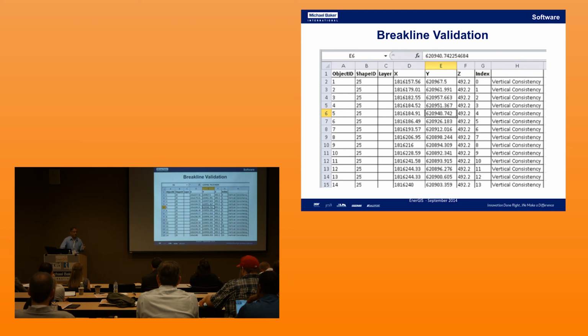And once you have the break line and the ground points, you take these two inputs to the post-processing or production stage, wherein you can create the derivative products like grids, contours, and other products that can be generated.